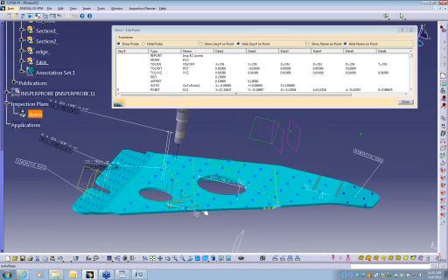and I can highlight all the points, and I can say make an inspection plan in VeriSurf, and then execute, and VeriSurf will prompt the user to measure each one of these points. And then inside VeriSurf, with a Faro arm or a Romer arm or a laser cutter or whatever, you could put an auto trigger mode on, and you can say, if I get within a couple thousandths of where this point location is, automatically take the point. So as you pass over the point with the probe, it automatically triggers when it gets to the point.